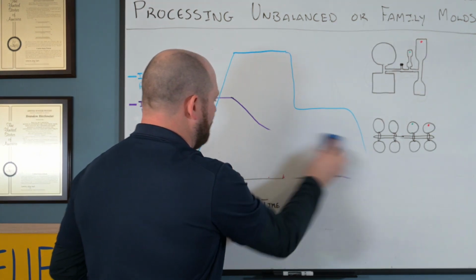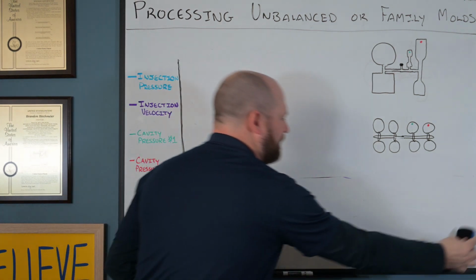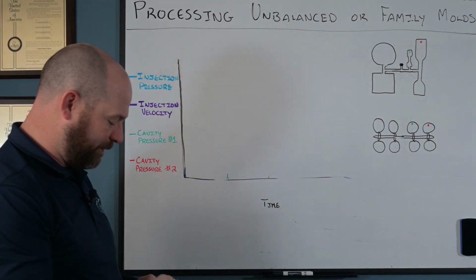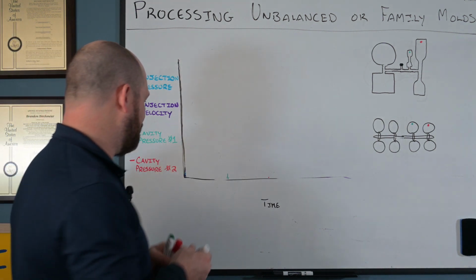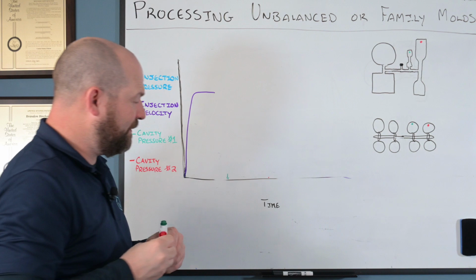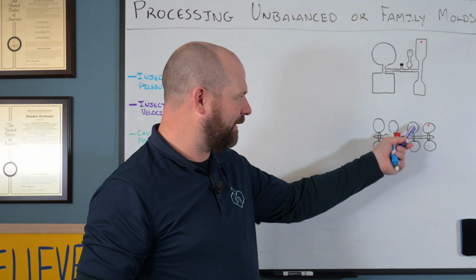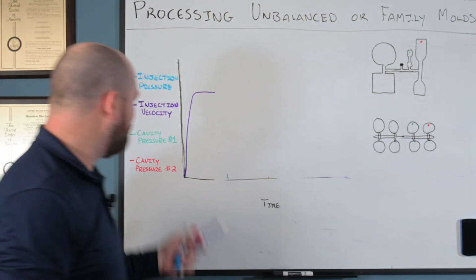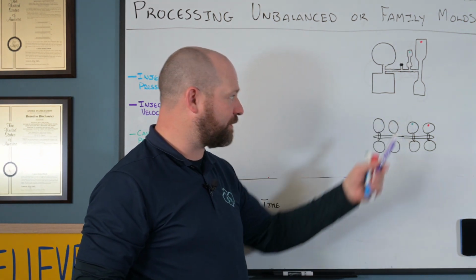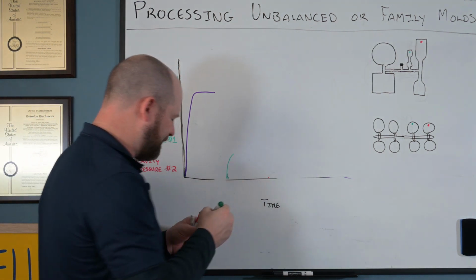Same approach. Again, we're going to be utilizing pack pressure in the process rather than a pack velocity, because pressure will be sensitive to the changes in the geometry in the tool in real time. So again, in this process, I'm going to use that fill phase speed, right? And as I do so, in this scenario, my green dot part will fill first, much shorter fill length than the red dot part. So again, I'm going to maintain fill speed, my first transfer into my pack pressure, 95% full on that green dot, on that green circle, like so.